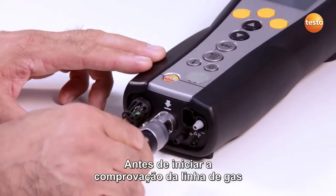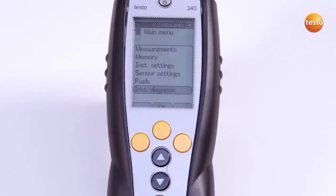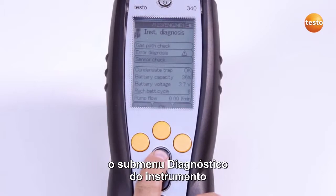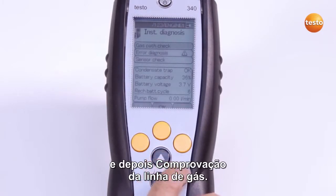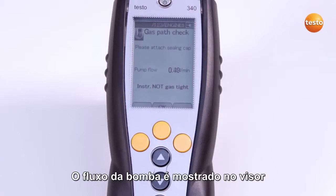Before I start the gas path check, I connect the flue gas probe to the Testo 340. Then in the main menu, I select the sub-menu Instrument Diagnosis and then Gas Path Check. The pump flow is shown on the display.